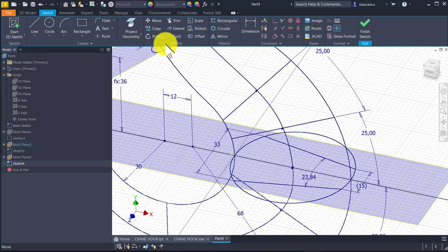Now I apply split on this arc and split on this arc. You saw there were 2 points there, and now I have one and another one. Why? I'll tell you after you think a little. Yes? Good. Why should I apply split? Because I don't want to have these two arcs as normal lines, but construction lines.